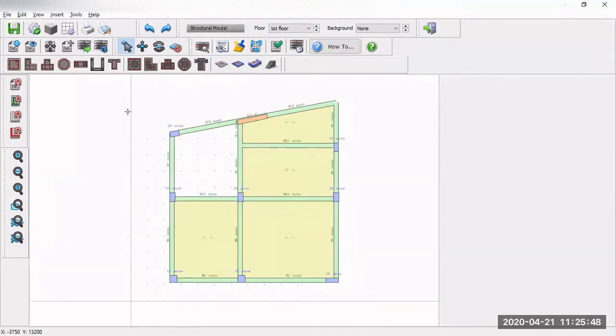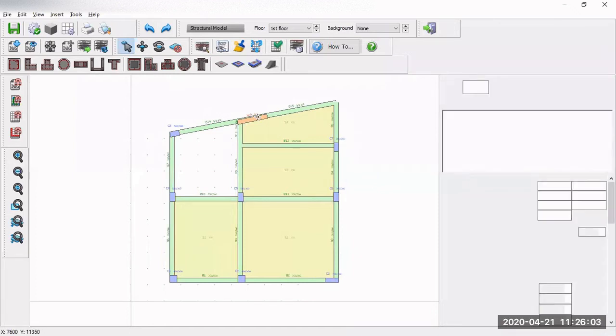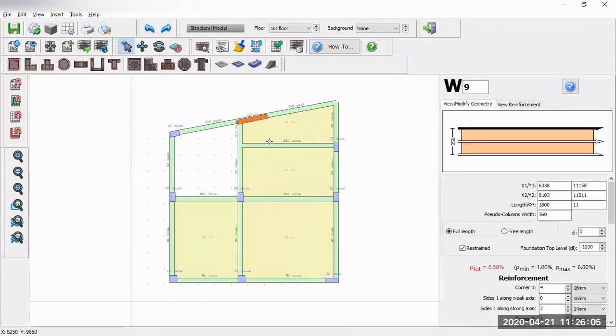Okay, so just now, as what I already find out is, realize is this walls is quite weak, and also this column maybe I need to think about to do some strengthening. So to do that, for this concrete shear wall, there's a lot of options. For this building, you can decide to maybe put another wall here, because this shear wall looks very thin, very slender. But in this wall here, I can show you we can put some maybe intervention,